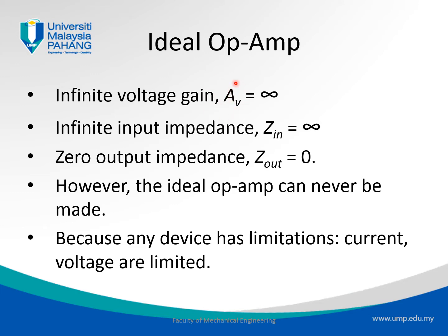So what is voltage gain? Again, if you look at the name, it is called an operational amplifier, so the basic task that it does is it amplifies signals. If I draw an operational amplifier, with the symbol that we've seen just now, it has 2 inputs and 1 output. The other terminals we can neglect for a moment. These 2 input terminals are plus and minus: one is the non-inverting terminal, the other is the inverting terminal, and here we have the output.